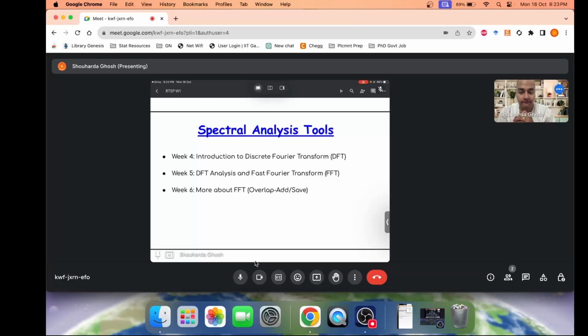Before understanding what overlap add and overlap save do, you need to understand how you deal with these signals in the time domain. When you have the continuous stream of samples coming in, you break them into various data chunks of, let's say, 10 milliseconds or 20 milliseconds. These are standard lengths. You store that entire set of 10 milliseconds of data into a buffer and then operate upon that buffer. So you take these batches of data and operate upon them.